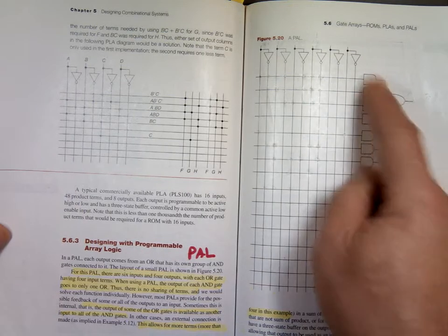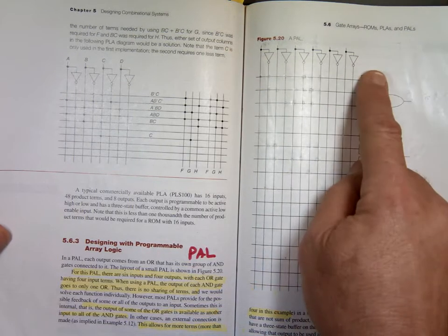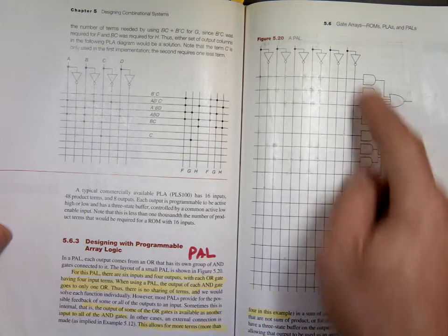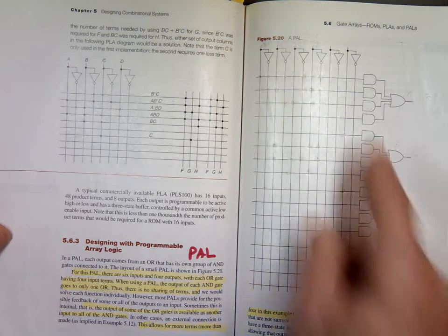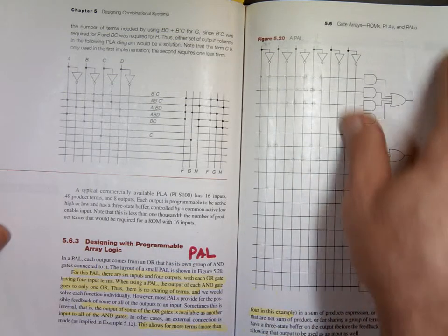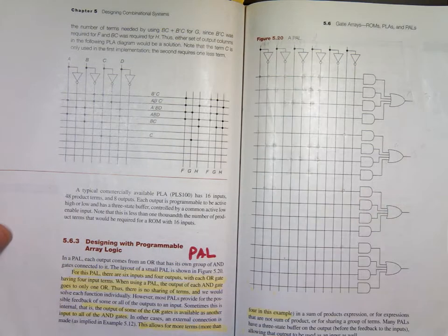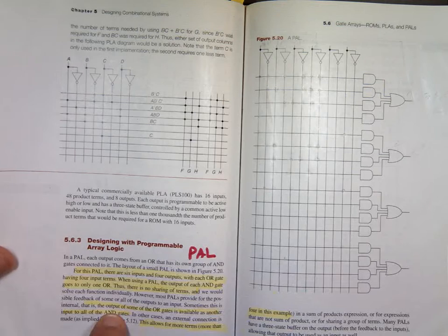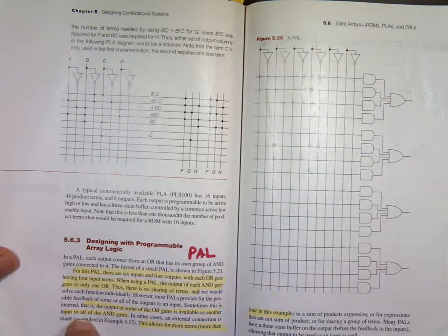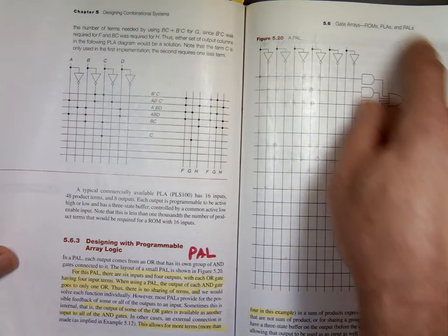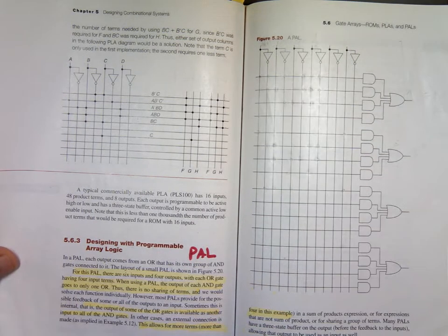Now sometimes you need, let's say F might need like 6 AND gates. If that's the case, since you only have 4, you got a problem. So what you want to do in a case like this, sometimes we take one of these outputs and feed it back in as an extra source of input. So here we go. The output of some of the OR gates is available as another input. So the output of this sometimes becomes an input. We grab it and use it again.